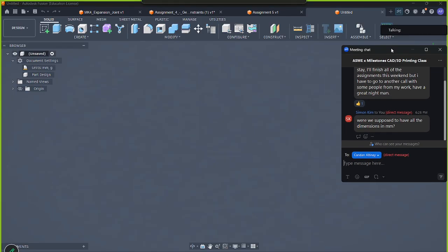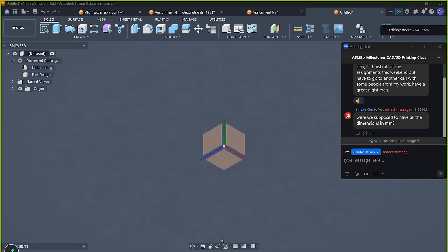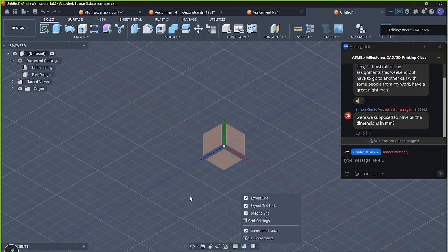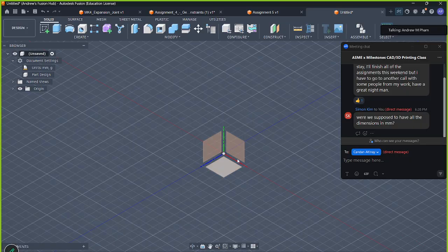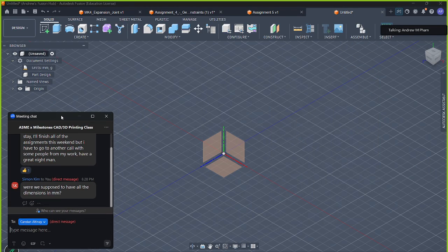By default, if I unhide the origin and also show the grid, you can see there are 3 default planes we can work off of, but for the loft, we want 3 more planes stacked on top of one plane. They should all be parallel to one of these planes. In this case, I recommend you create planes parallel to the top plane, just so the hair dryer's loft will be going upwards. But as long as it's consistent, it should be okay.